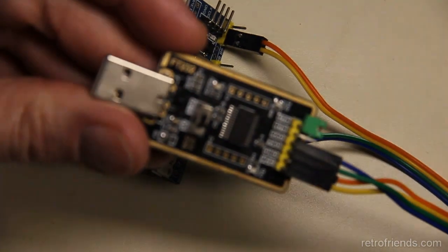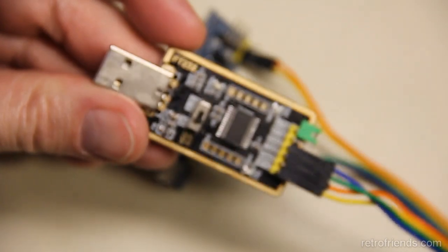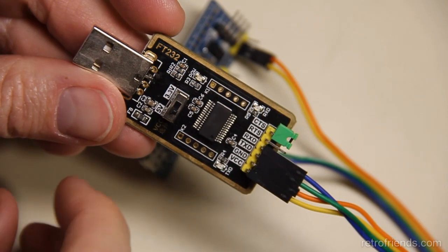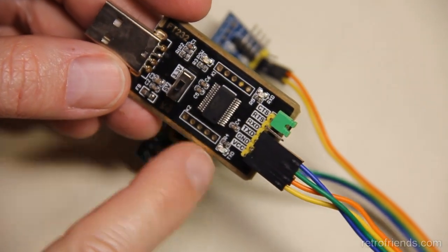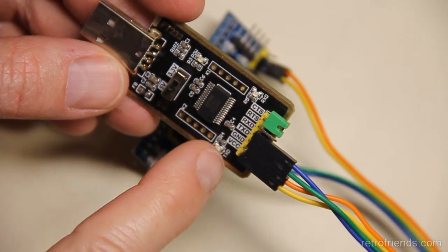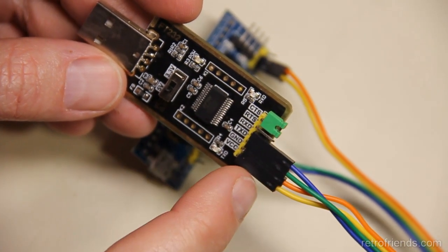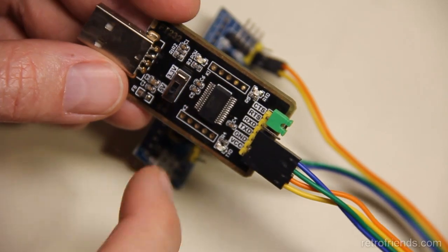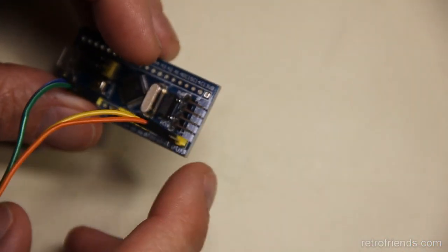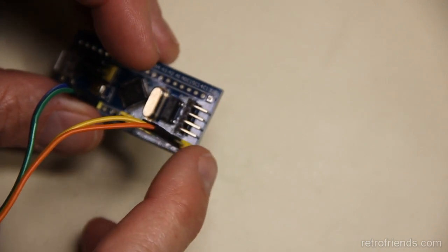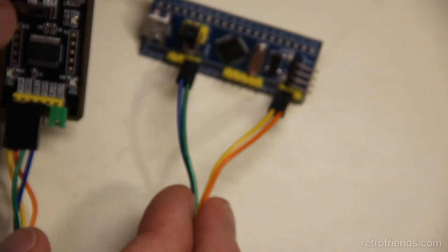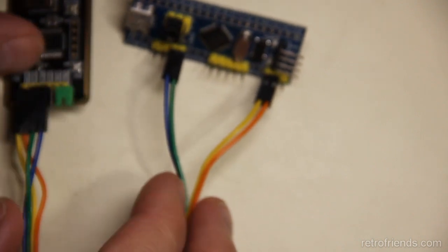Need to make sure you switch it to 5 volts if you have a switch, or if there is a 5 volt output. Sometimes there's a switch, sometimes there's a separate 3 and 5 volt output. In my case, it's one output that's switchable with this switch. So I wonder if you could program this with the 3.3 volt which is right there, but the FlashFloppy wiki indicates that it used 5 volts, so that's what we'll do.